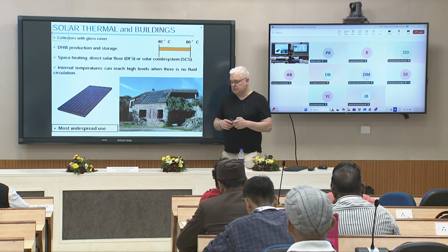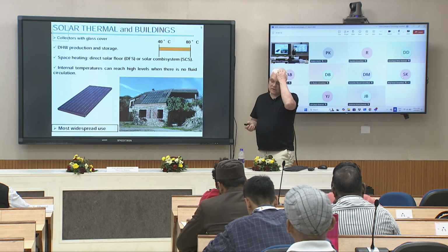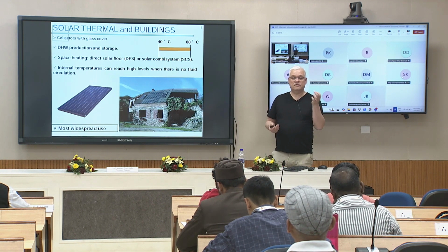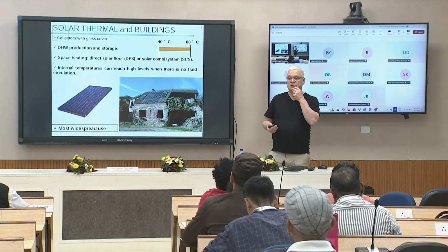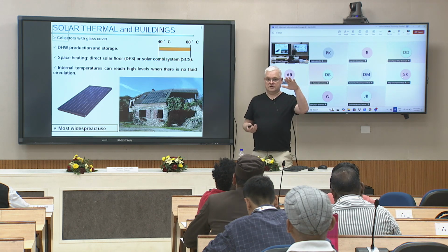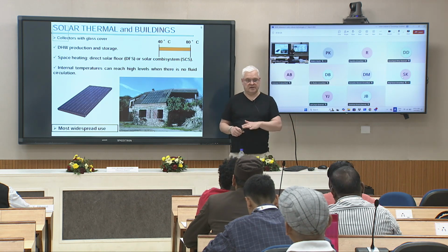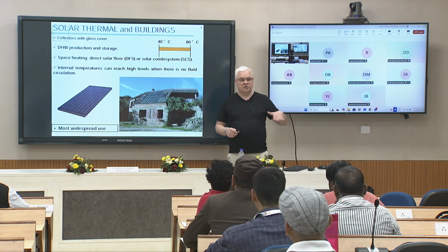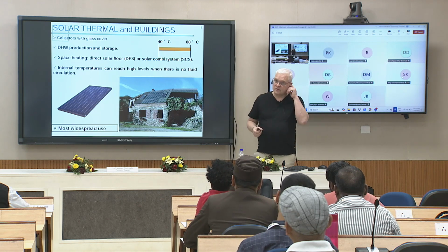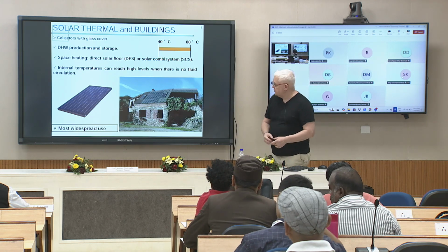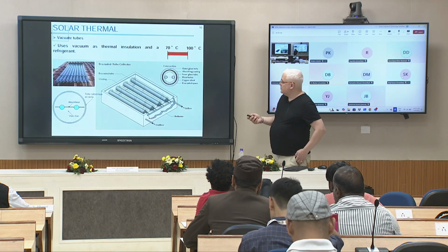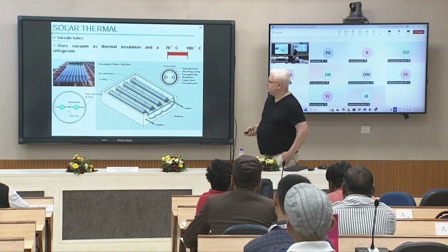Okay. It is very convenient with heating floor, because for heating floor you don't need to have a high level of temperature. It has to be very low, maximum 27 degrees at the surface of the heating floor. So it's good if it's well adapted, but also very expensive.